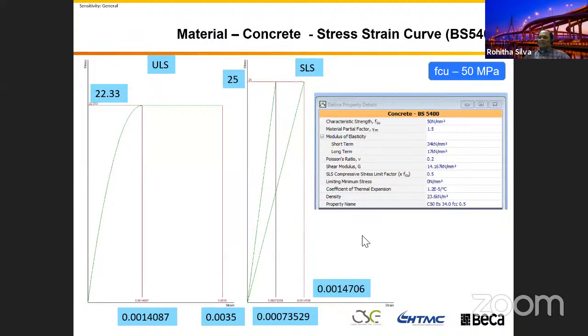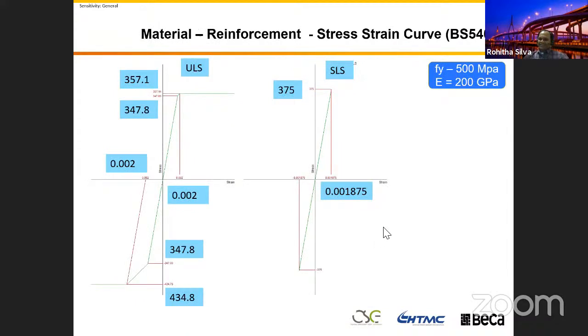Yeah, the same thing. I put this stress strain curve for your reference for the British standard, based on the BS code. I think you are all more familiar with the British standard than me. I used this one about 30 years ago, and this is the stress strain curve we use in the design. You can see that one in the British standard and the Eurocode. In these models we use a much lower stress level in the design.